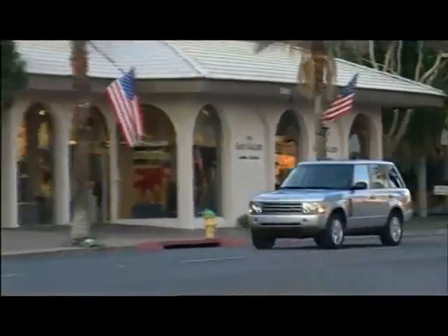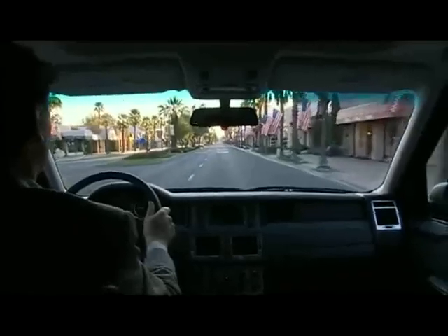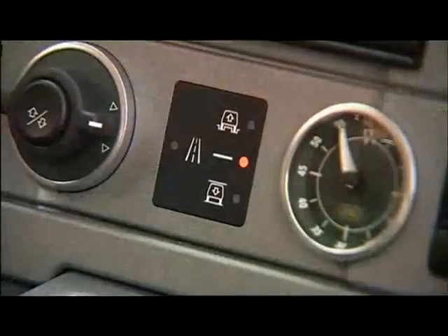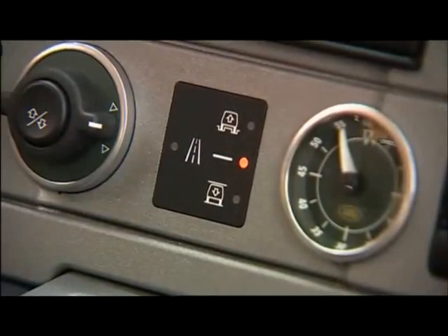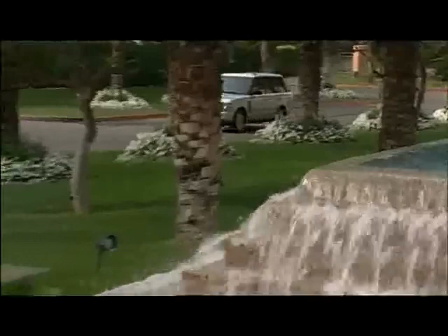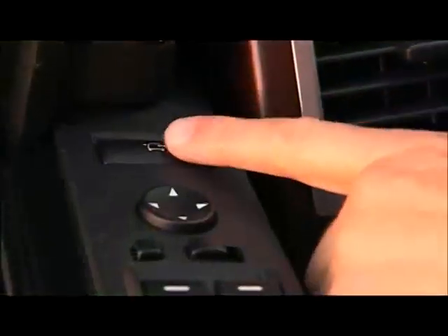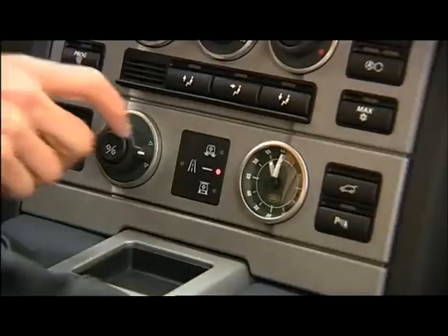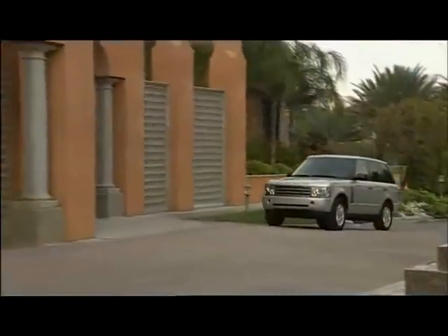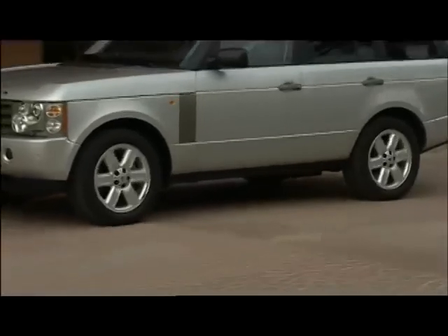Range Rover's electronic air suspension system has several functions. The first is varying ride heights. There are 4. The height indicator is located next to the selector. Standard is for normal everyday driving. Access mode lowers the vehicle 1.6 inches. It can be activated by the switch on the driver's door or by turning the ride height selector control on the fascia. When the speed drops below 15 miles per hour, it completes the command function while still in motion.